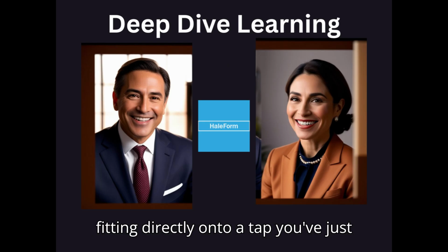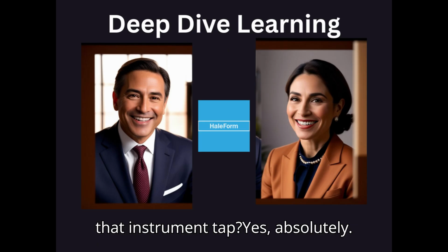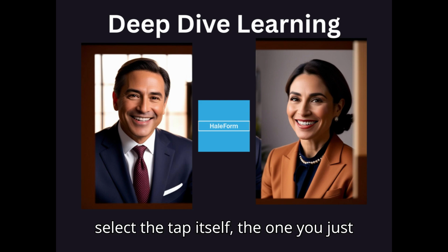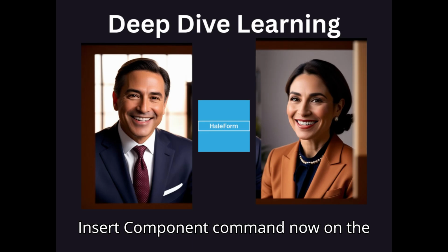Can you attach a fitting directly onto a tap you've just placed? Like putting a small valve onto that instrument tap? Yes, absolutely. That's a common workflow. You'd first select the tap itself, the one you just placed. Select the tap. Then you click the Insert Component command.